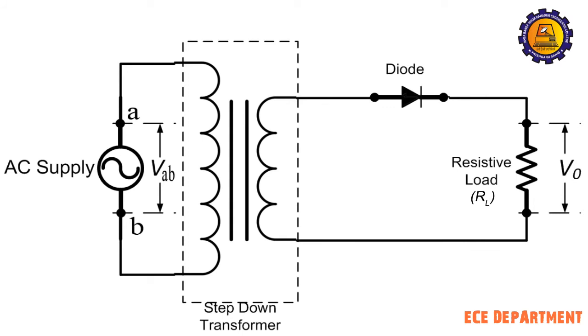The circuit diagram of half-wave rectifier is shown here. It consists of AC supply, a transformer to change the level of voltage, a diode, and a DC electric load, which could be an electronic device which runs on DC, a DC motor, or an electric bulb.